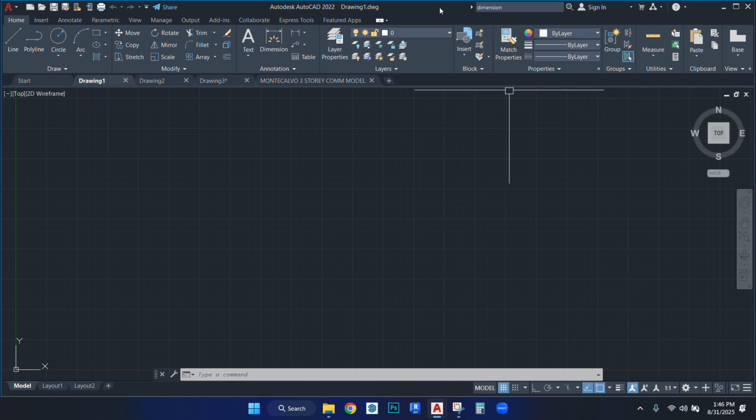Okay, now, before I go on further, let's talk about the different workspaces in AutoCAD. Right now, if you click here on the gear icon, it says workspace switching. Now click on the drop down arrow. We are currently using drafting and annotation. This is the default, especially good when you're just using 2D.